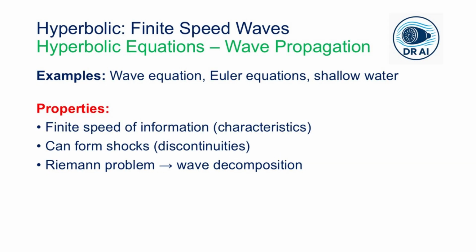And the third type is obviously the hyperbolic equations, which describe wave phenomena. The most exciting and challenging part of CFD is that the hyperbolic equations appear in compressible inviscid flow: generation and propagation of shocks, sound waves, expansion waves, contact discontinuities, and the Riemann type of problem. The Riemann problem is very central; it is a solution of the conservation law system with a discontinuous initial condition.